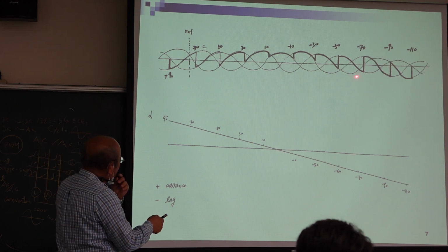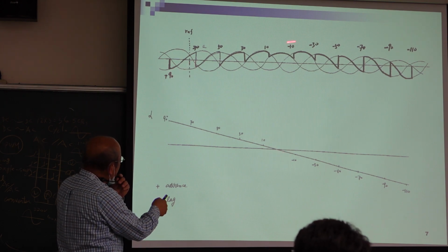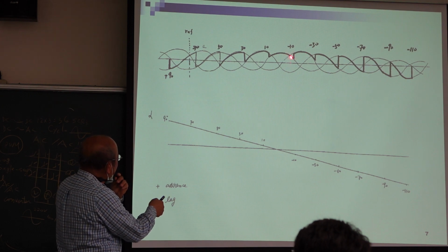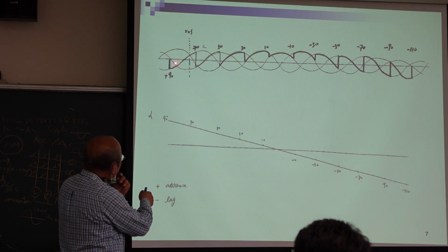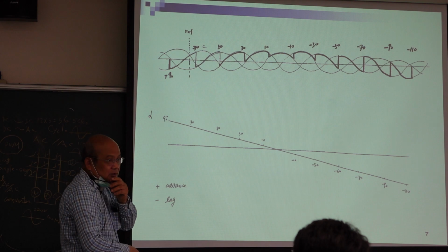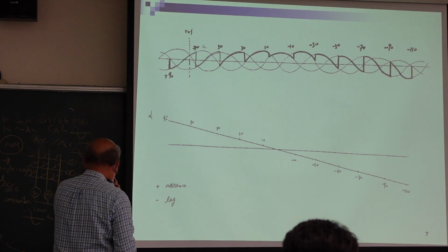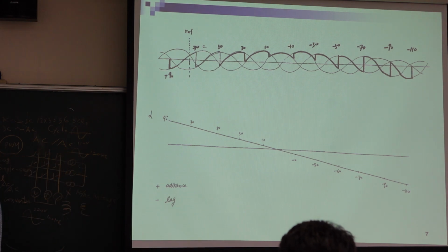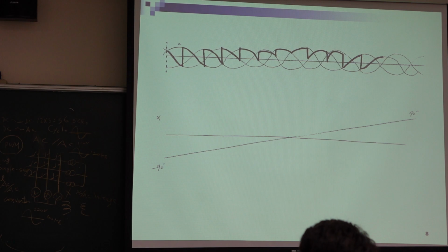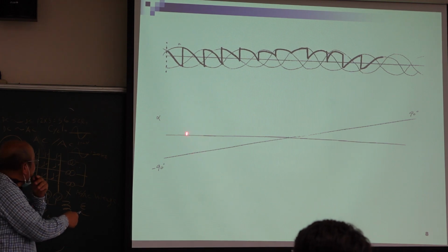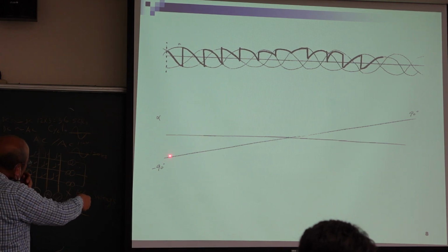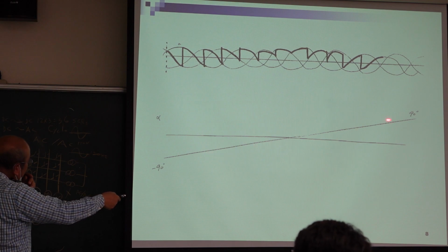The second disadvantage is that the harmonics are very huge. If I use my eyes, I find the fundamental is not very good. The harmonics are too huge. So then we can do some analysis. Another way is we change the delay angle from minus to plus.